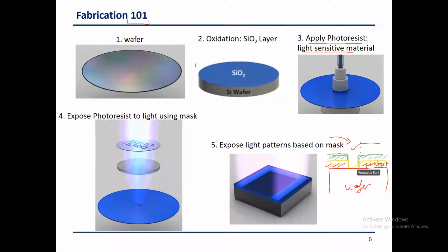A third process comes and brings a chemical that removes the photoresist. So we wash away the photoresist now using a different chemical, and we will end up with the oxide in this pattern. So now I have the wafer insulated everywhere except in places where I want to do processing.